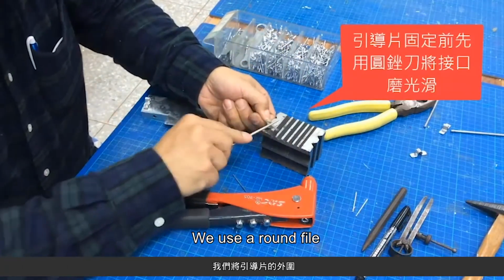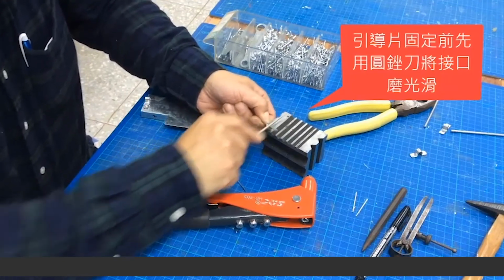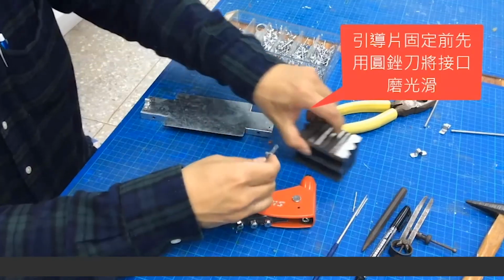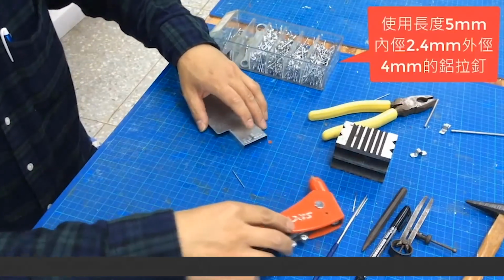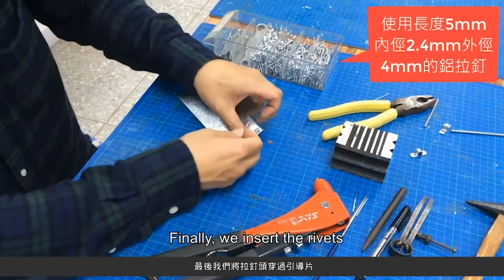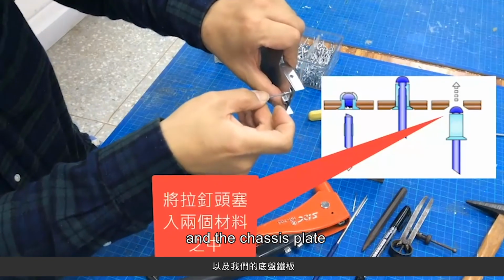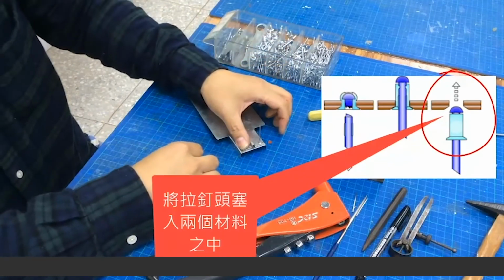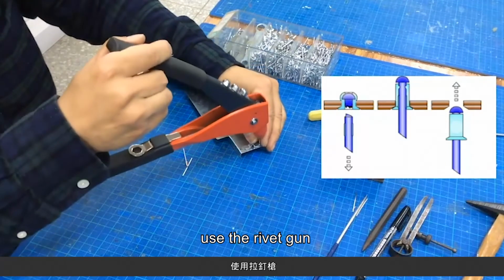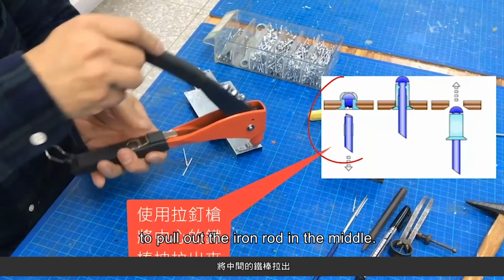We use a round file to smoothen the edges of the guide plate so that it can move on the cable with ease during future testing. Finally, we insert the rivets and the chassis plate. After the two plates are buckled together, use the rivet gun to pull out the iron rod in the middle.